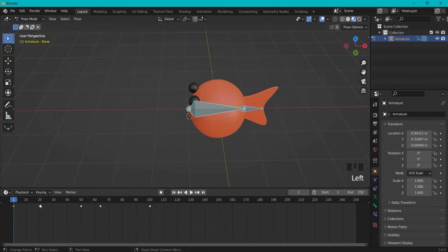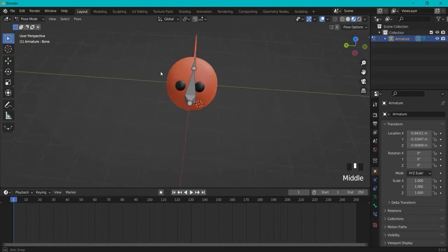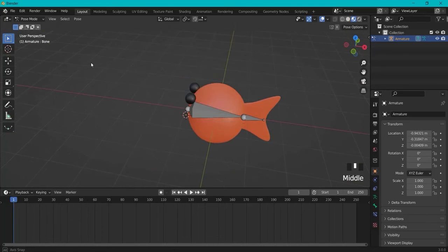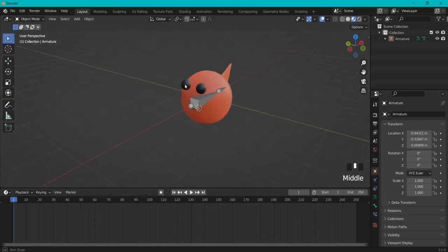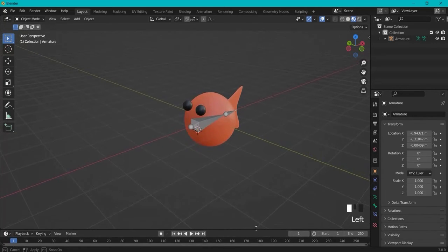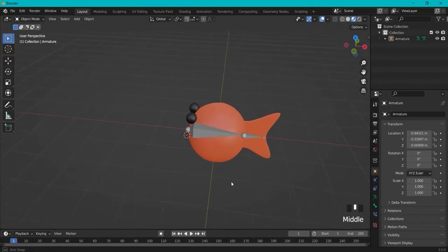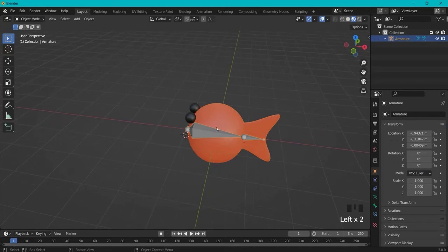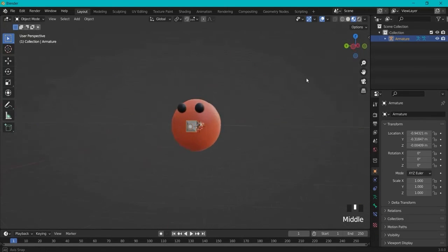You can move these around, you can edit these, but let's say you want to delete these, select them, hit the delete key, and in this view, with A, everything selected, Alt R will reset the rotation, Alt G the location, and then Alt A will deselect everything and just remove the selection. Back into object mode, you just have your fish here and you can move this down. So these are the very, very basics of modeling, rigging and animating a basic low poly fish.